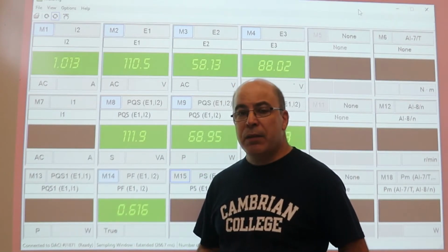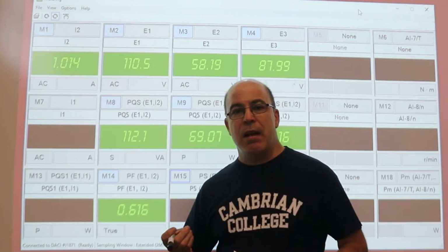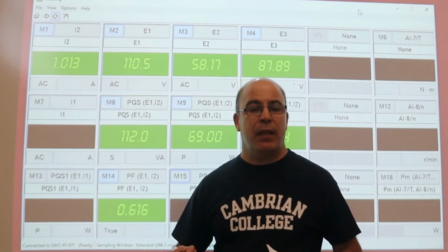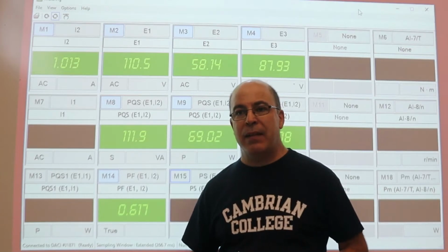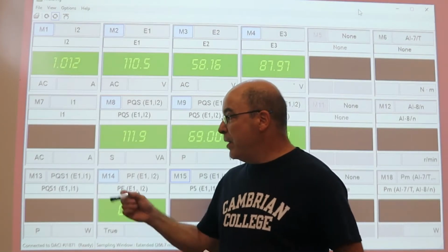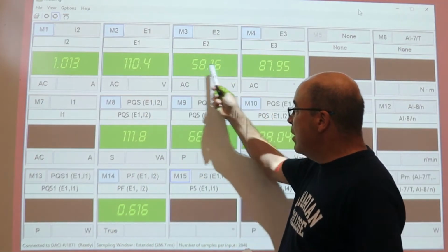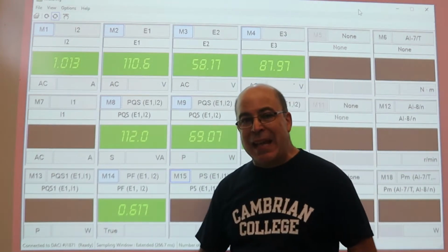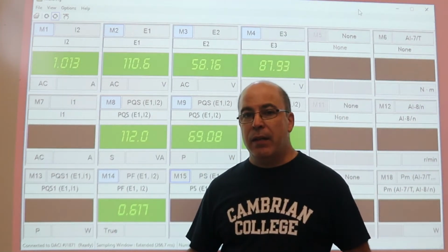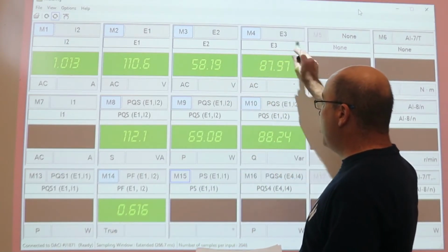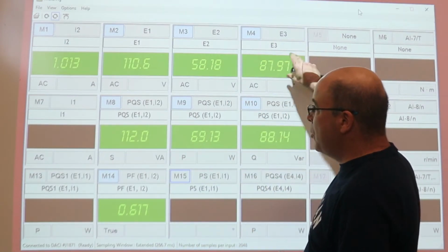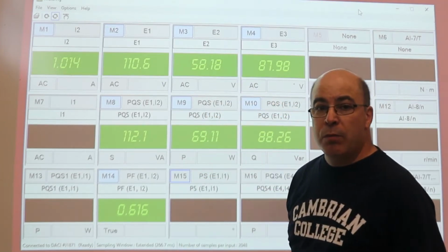Unfortunately, with the inductors, we can't measure inductive reactance. We can only calculate it. So my ability to fine-tune the amount of inductive reactance is fairly limited. This is why we see that the voltage drops are not exactly what we calculated, but the trend is there. You'll see that the voltage drop across the inductors is much larger than that across the resistive load module.